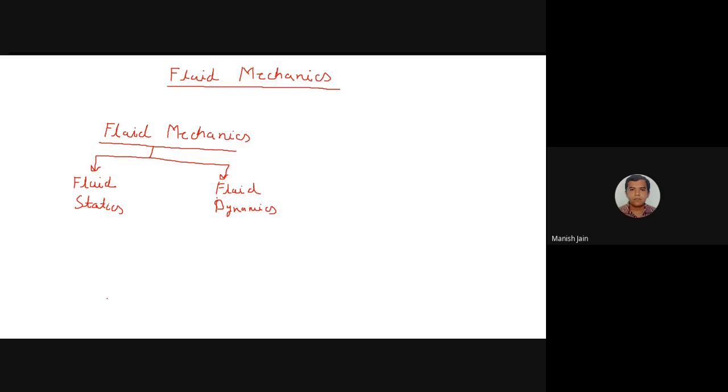Like when you explore oil from the earth, from the oil wells, that oil does not come as pure oil, it comes with mud and water. So first you have to separate the mud and water from the oil. You can do that by using some type of equipment which works on the principle of fluid statics.